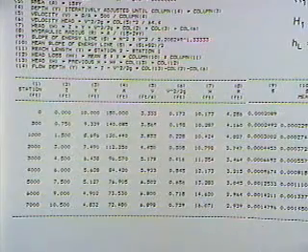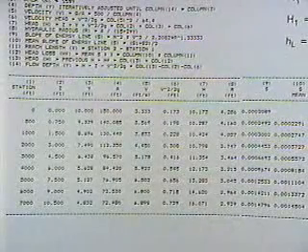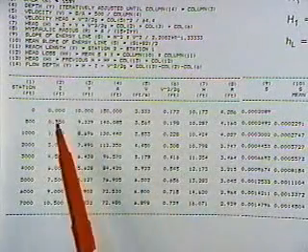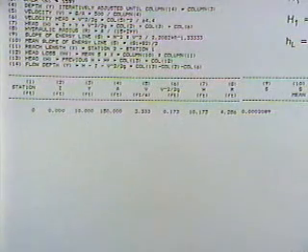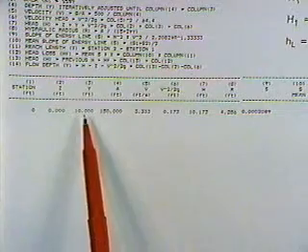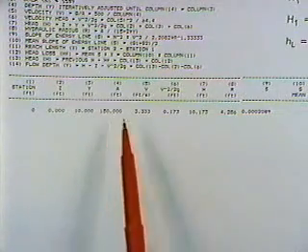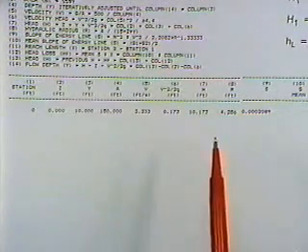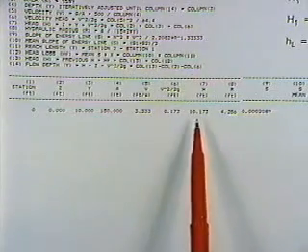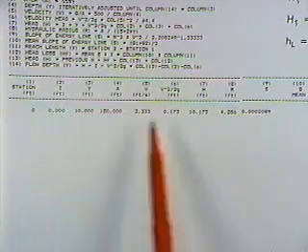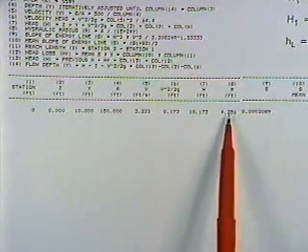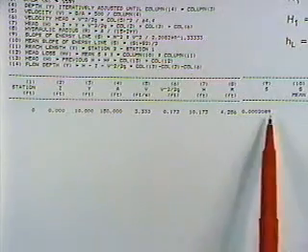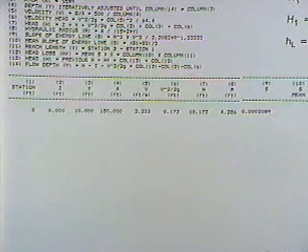And I don't think I'll take a whole lot of time on this simply because we've got so many things we need to cover tonight. But basically what we're doing is in the first line of the computations, we're given the depth of 10 feet, and given that once you know the depth, you can compute everything. You can compute the area, the velocity head, and then the velocity head plus the depth plus elevation head, the total head. And then you can compute the hydraulic radius, and you can compute the slope from Manning's equation.